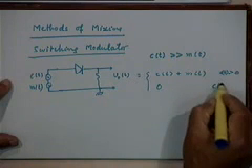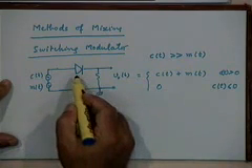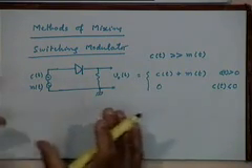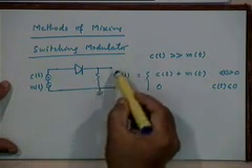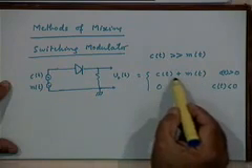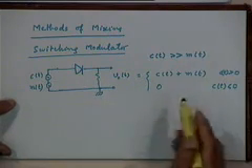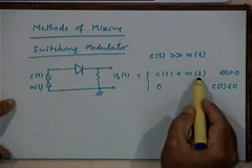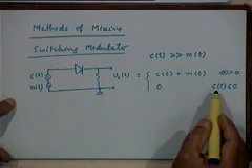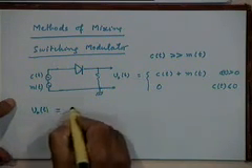When the carrier waveform is going through its negative half cycle, it is less than 0, the diode will be reverse biased and the output voltage will be 0, right. So this is a kind of switching action. Basically what you are doing is you are getting an output voltage which is a product of the input voltage and a 1-0 sequence, right. In this half you are multiplying the input voltage with 1, in this half you are multiplying the input voltage by 0, right. So it's as if your output voltage v0(t) is the product of the input voltage waveform